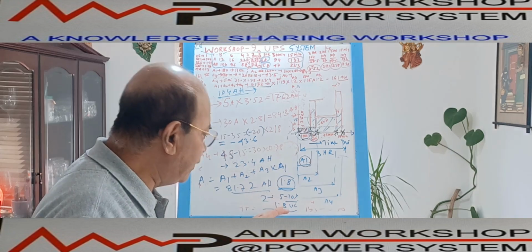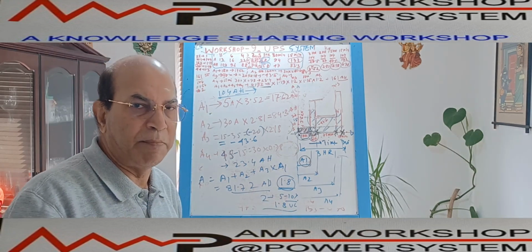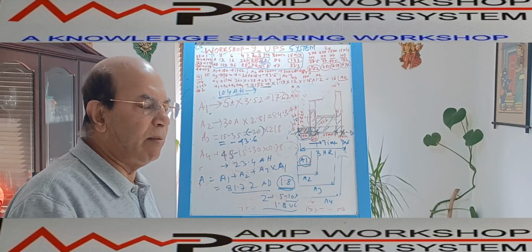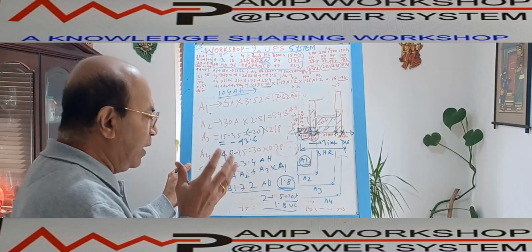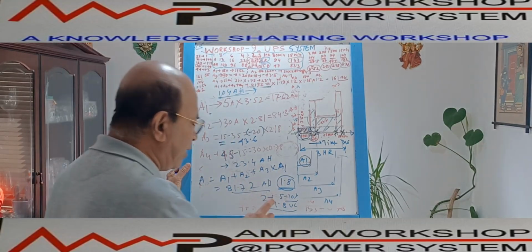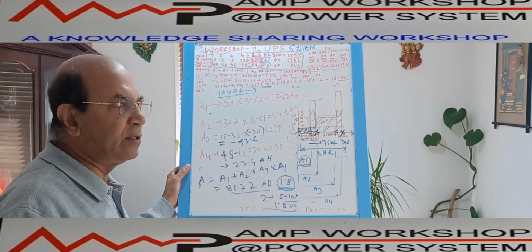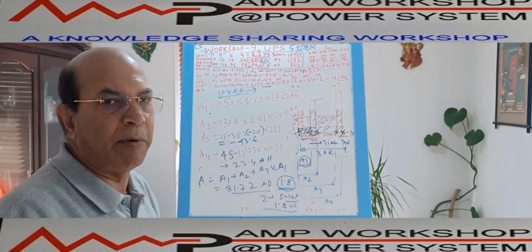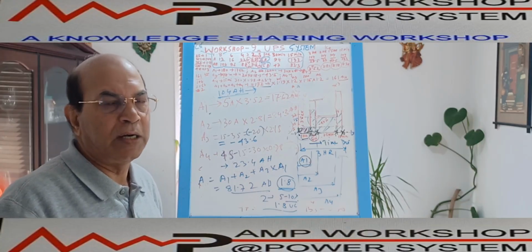So at this voltage, how much ampere hour can it deliver? That we have to discuss with the battery manufacturer. Normally, most manufacturers recommend that if the battery discharge is limited to 1.8 volt, meaning 90% of the rated nominal voltage, the battery will be able to deliver only 80% of its capacity. The balance 20% capacity, it will not deliver.